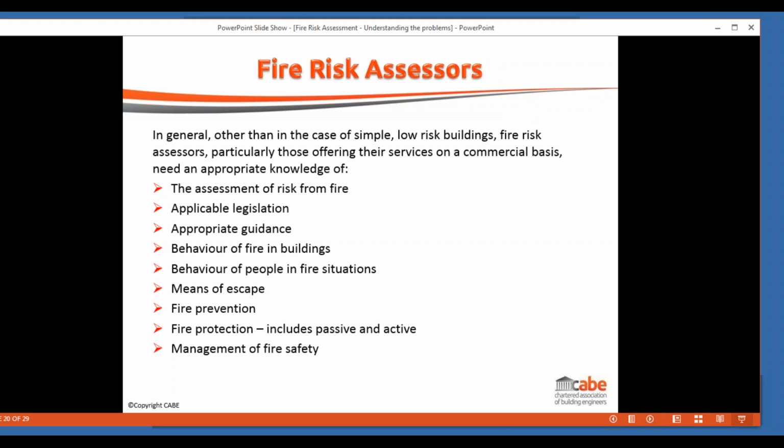In basic terms, some of the things you have to start looking at are what the legislation is. I notice there's a question come in asking, do you know if it's a legal obligation in Scotland to carry out fire risk assessment in general needs communal areas in flats? Generally, in terms of the legislation, there's a lot of debate about flats. The flat is covered by the Regulatory Reform Order in England and legislation elsewhere, and as a result there is a need to do a fire risk assessment on those common areas in some sort of control. The question is who's responsible for those areas.